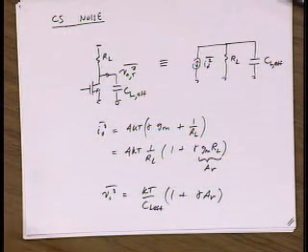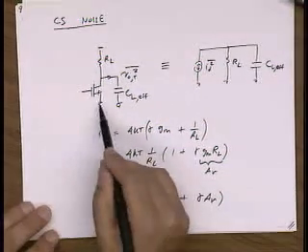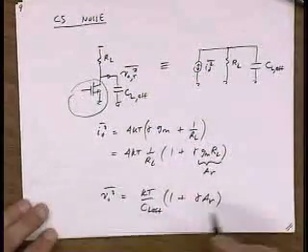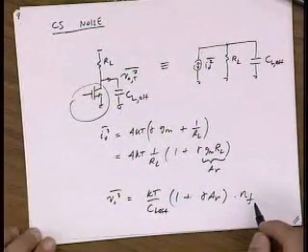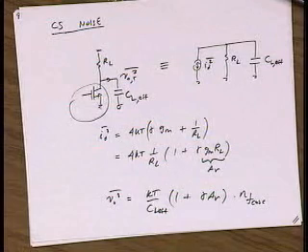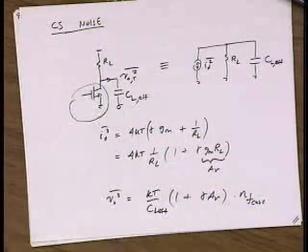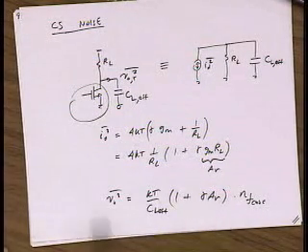It doesn't change by much. Well, at high frequencies, we know the cascode starts contributing. But we've all analyzed that problem. If I replace this with a cascode, then there's a little extra factor, let's call it NF cascode, which accounts for the extra noise you get from the cascode. But it doesn't fundamentally change the answer, right? That's the important point. Well, what about when we put feedback?